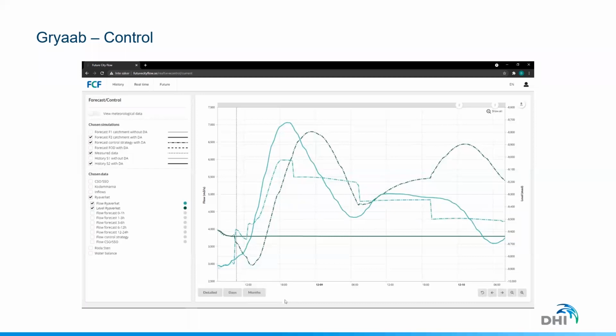in the sewer network and in pumping stations, and the corresponding values in the hydraulic model, Future City Flow uses data assimilation techniques before each simulation, and we can adjust the forecast according to identified patterns of deviations before and between measured and simulated values.